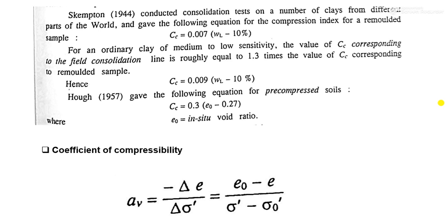Again, another equation has been given for ordinary clay or remolded samples of ordinary clay. If we need this Cc value, we can calculate it from this equation. We just need the liquid limit value.